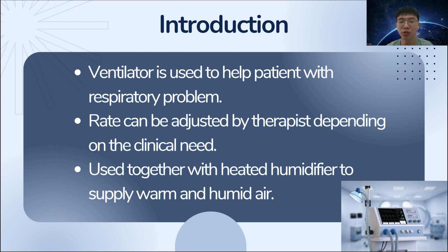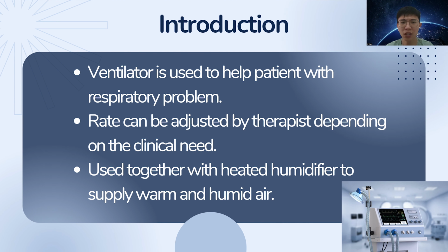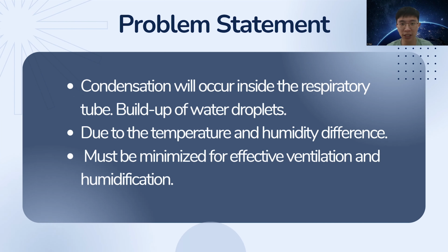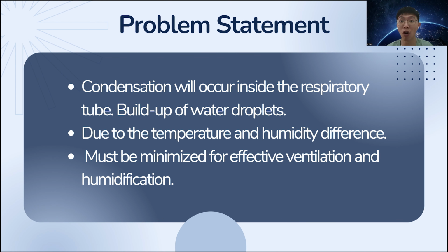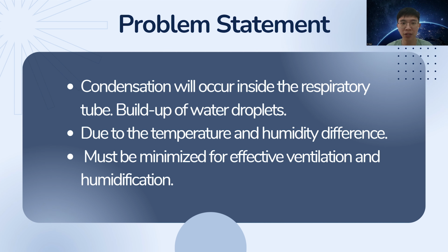Usually, it is used together with heated humidifier to supply warm and humid air. However, the problem arises where condensation will occur inside the respiratory tube. The water droplets will be built up due to the temperature and humidity difference. Condensation problem must be minimized for effective ventilation and humidification.